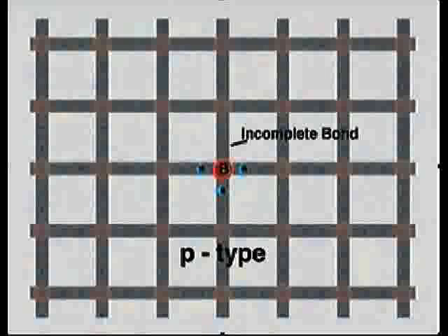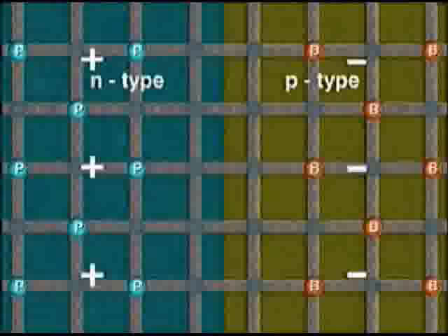One can make p-type silicon by adding impurities such as boron with only 3 valence electrons. It forms only 3 complete bonds with the neighboring silicon atoms, leaving 1 incomplete bond which has the ability to catch an electron, using a nearby electron from the valence band. This neighboring electron leaves behind a positive hole that can diffuse through the crystal at ordinary temperatures. With an extra electron near the boron, the region has a net negative charge, and because of this, the boron is called an electron acceptor.